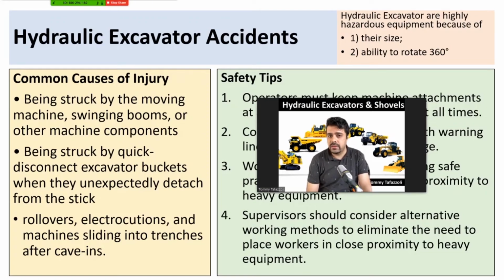Okay, so in detaching them, a lot of care should be taken. Also in attaching them, to make sure that they are firm enough. There is no risk of falling, especially when you're working with heavy cuts. So it means very tough type of soil in which a lot of energy is exerted into the joints between the bucket and the stick.